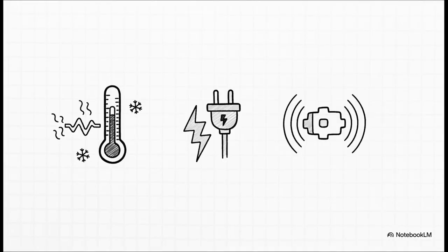It comes down to three main things. First, just normal temperature swings in the factory. The datasheet for the sensor even says that can change the sensing distance by up to 10%. Second, tiny little variations in the machine's supply voltage. And third, and this is a wild one, even imperceptible vibrations from other equipment nearby can cause microscopic changes in that 1.5 millimeter gap, pushing the dog in and out of that marginal zone.